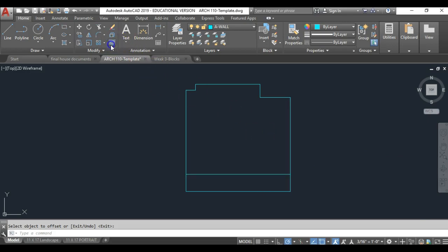So I'm going to go to offset, and it's 13 foot 10, enter, from the secondary line up. And it is 10.8 over, which is the same as this. So I could do offset, and instead of writing 10.8, I can just click here and click there using my object snaps to make it 10.8, and we can see it's lining up perfectly, right?